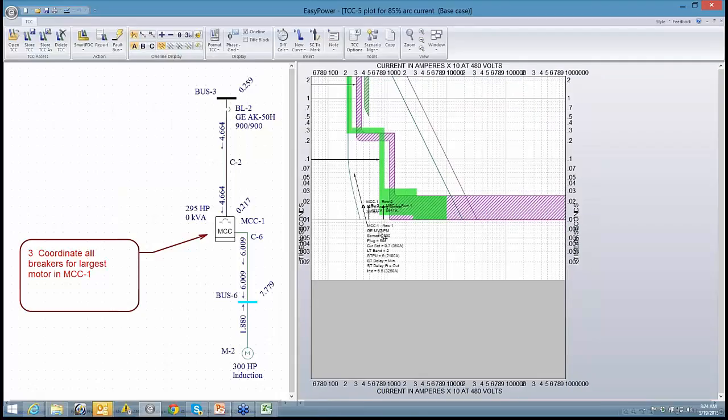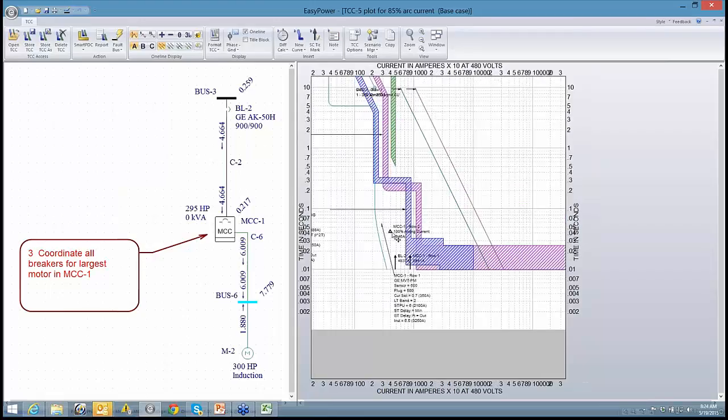All right, and so that's why you have to be a little bit careful with this. What you see here is this triangle is the 100% arcing current for row 2, and because I want it to be the first one to trip, I'll bring down its trip characteristics or its set point. So now I have separation between row 2 and the main breaker.